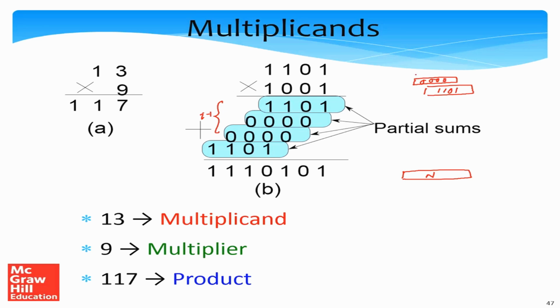Then we shift it one step to the right, and then we again add 0000. Then we again shift this one step to the right, and then we again add, which is exactly what we are doing. So instead of shifting the partial sums one step to the left here, what we can do is shift the partial product, which is our current accumulated set of partial sums, one step to the right, and of course not lose any bits, and keep on adding the multiplicand if need be.